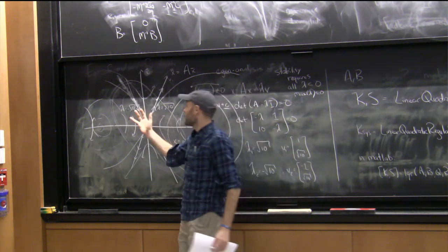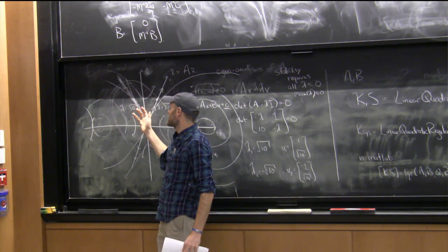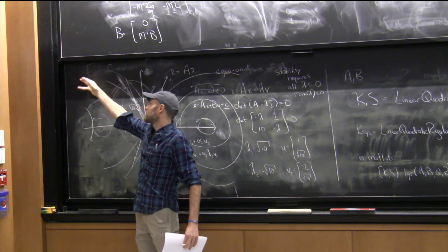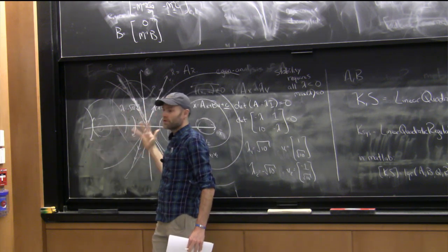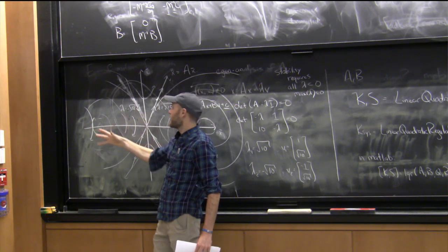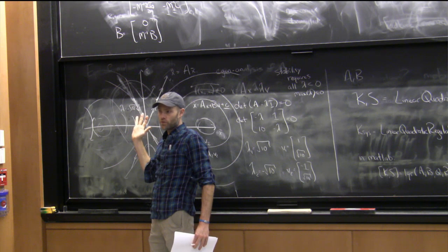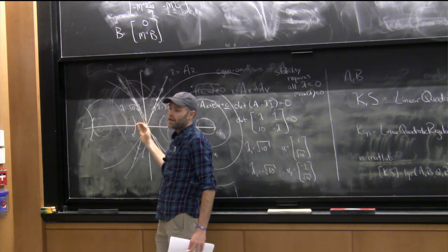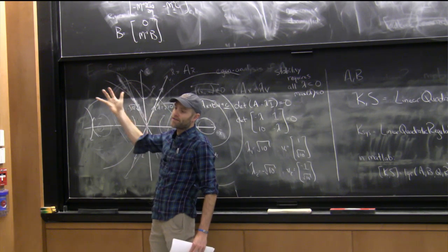So in fact, one algorithm that's out there is to actually make a network of LQR controllers, some of them that move along the trajectories that try to come in here, and some of them that just cover fixed points, so that you can eventually cover the entire space with linear optimal control. And if you have the two components of knowing how to design the linear controller and then being able to check rigorously when it works for the nonlinear system, then you can patch things together.